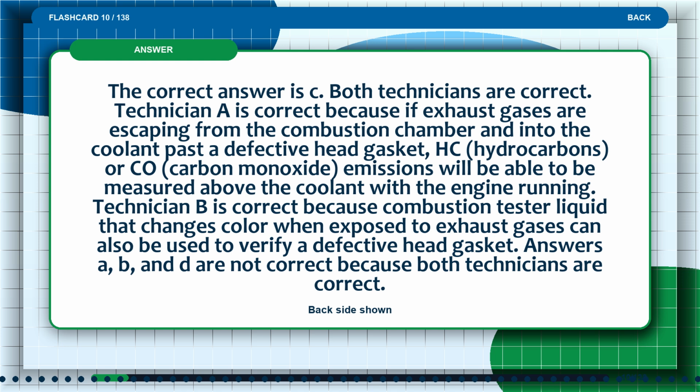Technician B is correct because combustion tester liquid that changes color when exposed to exhaust gases can also be used to verify a defective head gasket. Answers A, B, and D are not correct because both technicians are correct.